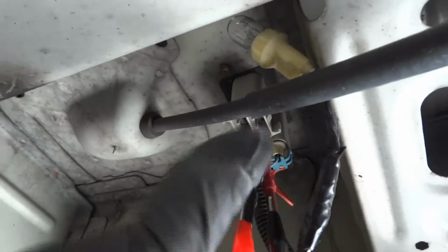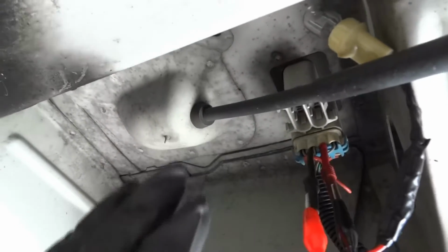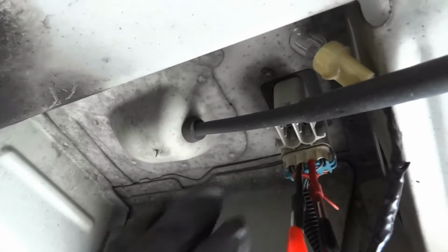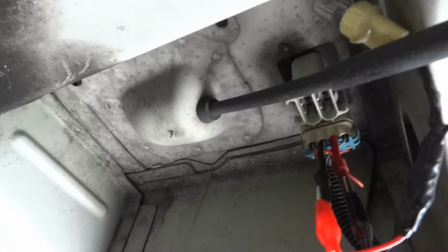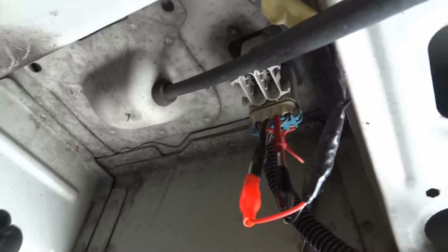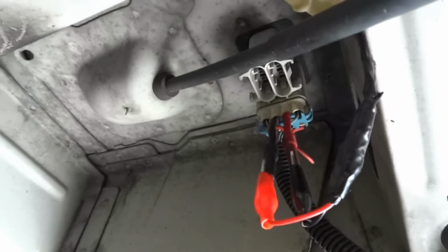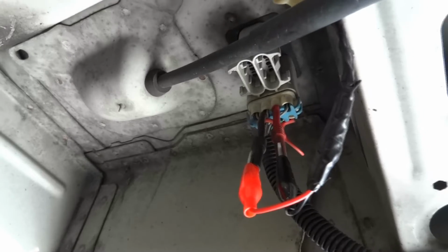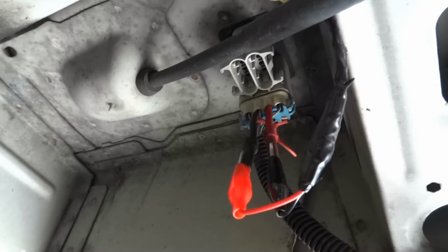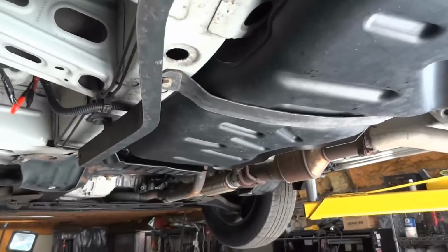And since after installing this test light in the vent solenoid circuit, our trouble code was able to get cleared, that tells me that the circuit from the solenoid all the way to the computer is good. Our problem is just the open vent solenoid. Now, if you still have any questions, I'm gonna show you the vent solenoid on the wiring diagram. And after that, we're gonna have to lower the fuel tank a little bit so we can get access to the vent solenoid, okay?